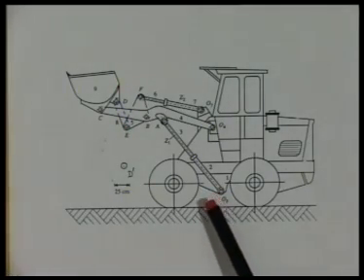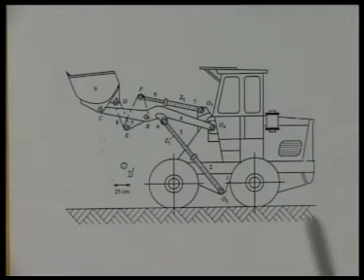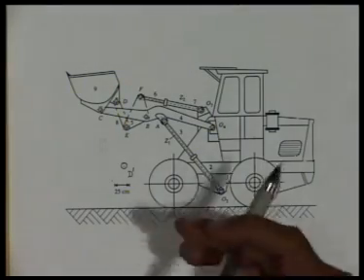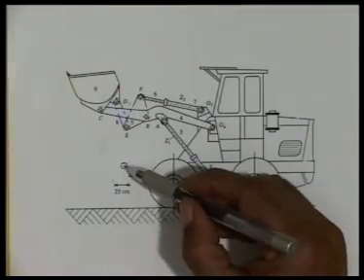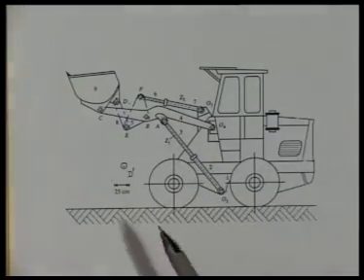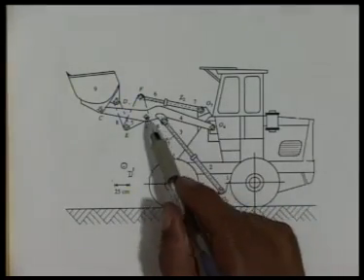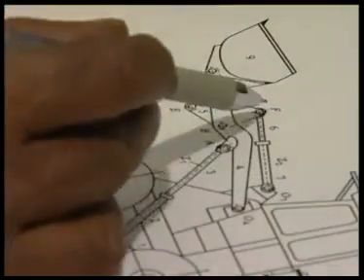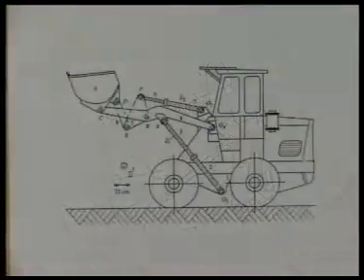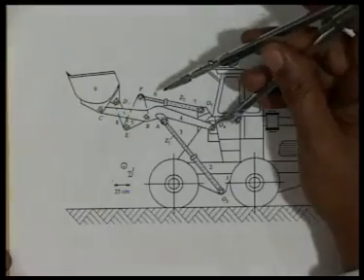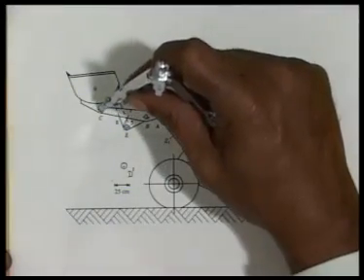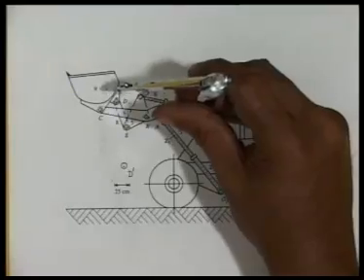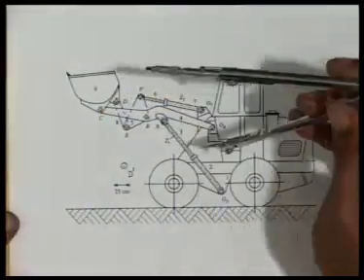This is the figure of the same front end loader which we are discussing right now. As I said earlier, the point D has moved to this point which I call D1, and the objective is to find the location of all other movable revolute pairs, that is at A, B, E, F and C. We should note that O4C being 2 revolute pairs on the same rigid link 4, the distance O4C cannot change.